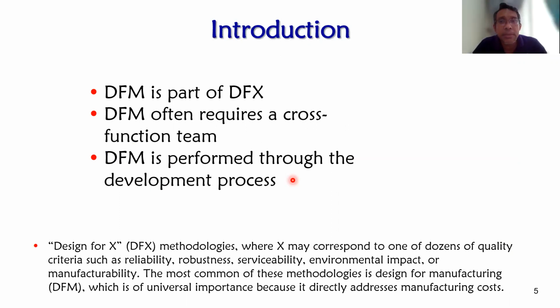Okay, we go for the introduction. We will learn about design for X, because DFM is part of DFX. Design for X is about quality. The DFX methodology is where the X corresponds to a dozen quality criteria such as reliability, robustness, serviceability, environmental impact, and manufacturability.